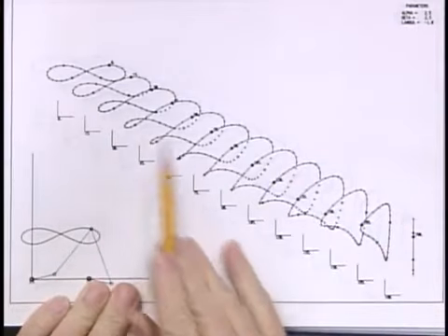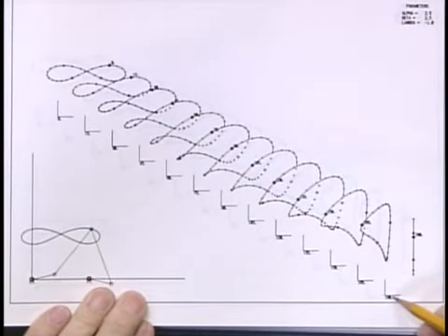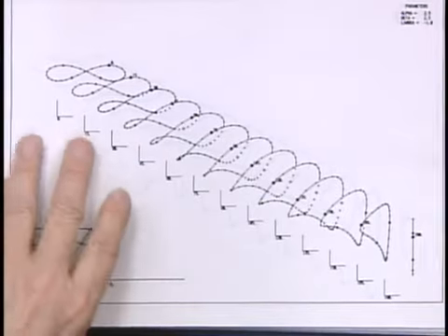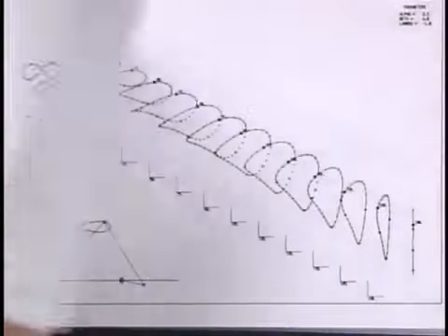They were all negative 1 gear ratio. With a 180-degree phase angle, I get a perfect straight line, and this is not approximate. This is on the money. So this will generate an exact straight line. Kind of an expensive way to get the straight line because of the gears, but nevertheless.